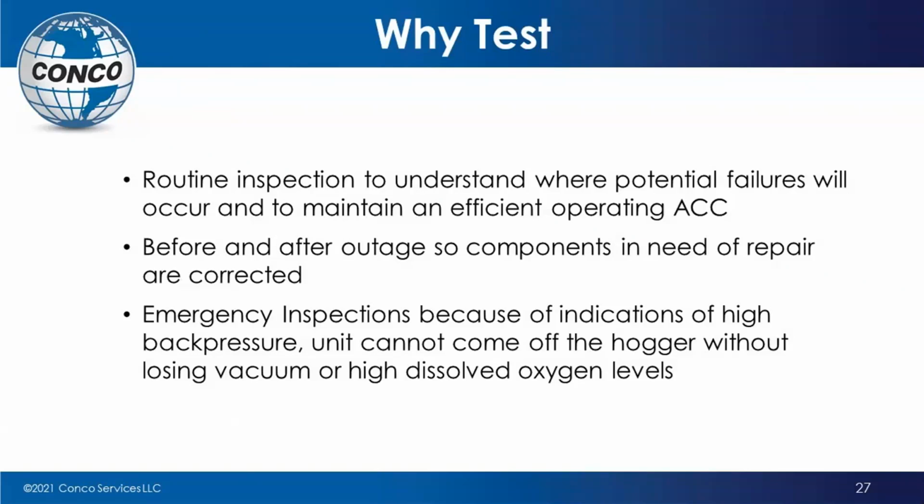Why a routine inspection? Because like I said, you know you have air in-leakage. When you go into an outage, if you go in and do a leak detection right away, you can find that small leak that you didn't know you had because your air removal system is capable of removing that air. But you don't know how bad it's going to be in July. So if you go into that outage and you know what you've got to fix, you can find it and repair it.